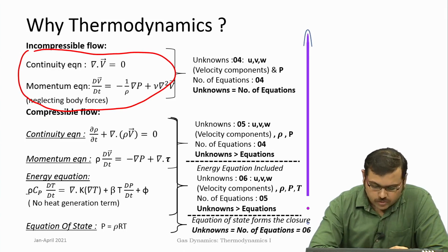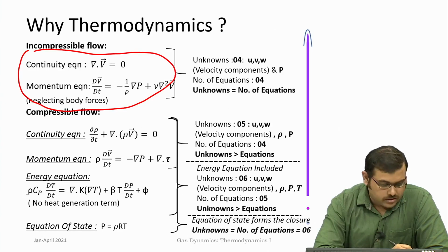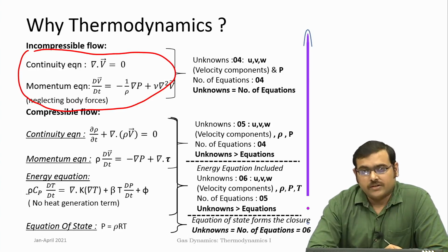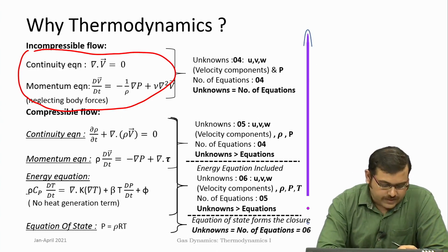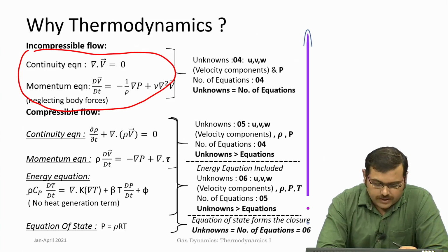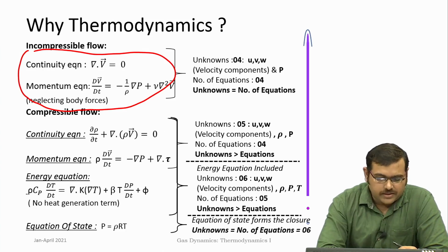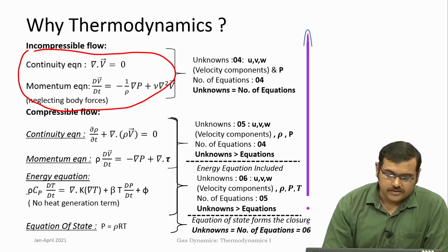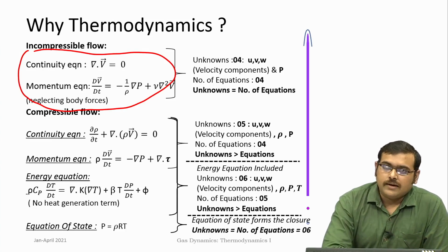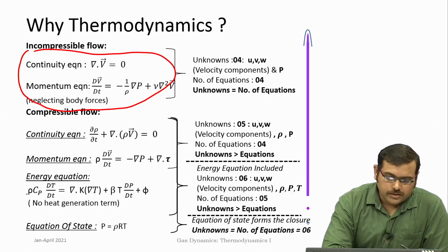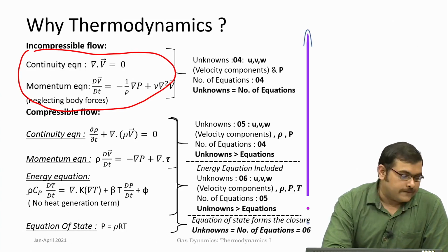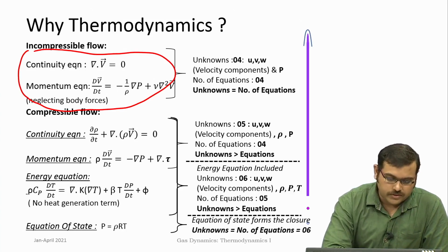That equation is supplied through the equation of state. Both the energy equation, through the definition of enthalpy, which is what comes into the picture here, and the equation of state, which in this case is the perfect gas ideal equation of state, P equals rho R T, bring in thermodynamics. Without these equations, it is not possible to solve compressible flows. So thermodynamics is an integral part of understanding and analyzing compressible flows.